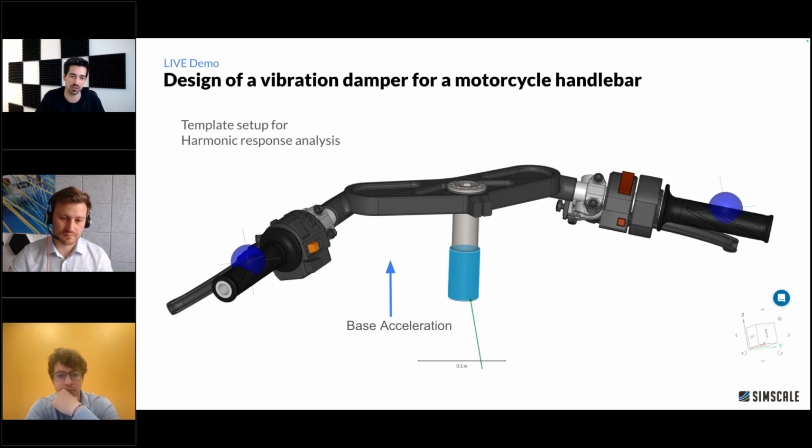But this was unnecessary in this case, because we're not that constrained, as you might be on your local computer or local hardware, where you must optimize for a reasonable mesh size. I mean, if it's 5 million cells, then so be it. It might take longer. And if I don't want to spend the time, then I spend some manual time to clean up the model. But in this case, I used a standard setup, standard mesh settings, nothing changed.